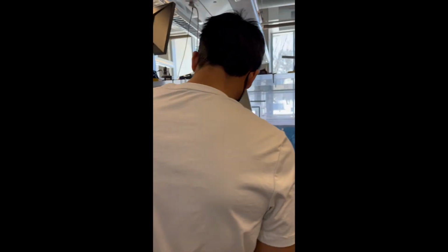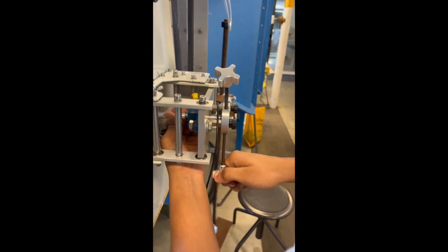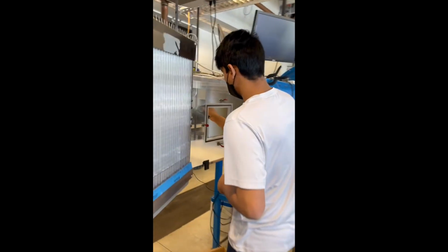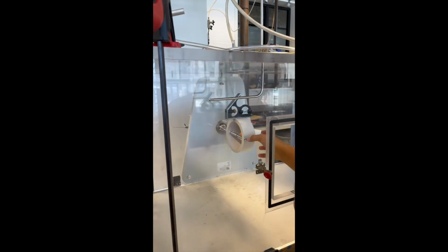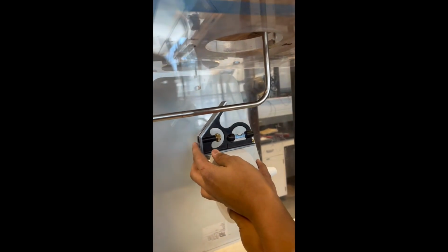So for the wind tunnel testing materials, I had the 5 3D printed nozzles at the 20% truncation increments. I had 1/4 inch and 1/2 inch drill bits. I had 1/4 20 screws and nuts. I had the level to ensure that the nozzle was level in the wind tunnel, and I also had the strut for the nozzle attachment in the wind tunnel. The two main instruments used for data collection were the manometer for pressure measurements and the force load cell, which allowed me to quantify the forces acting upon the object by the wind.